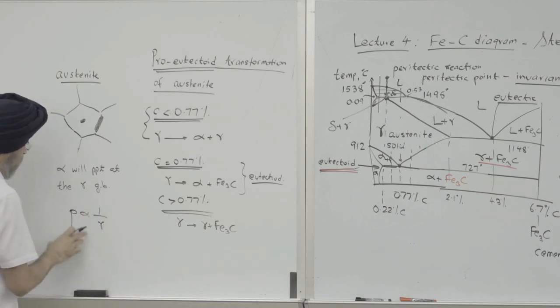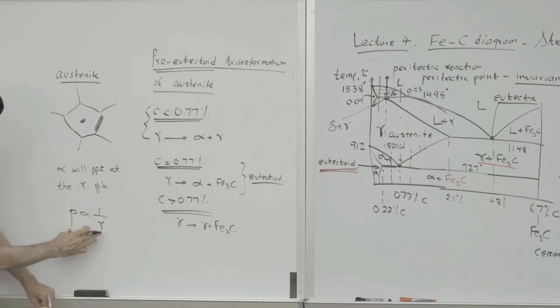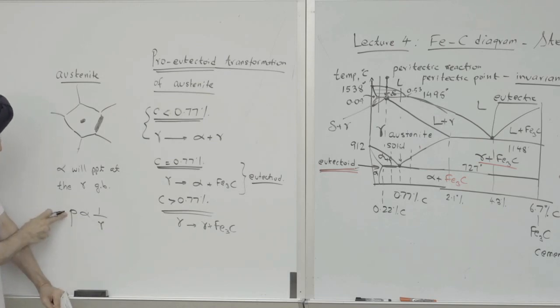So that's for gas bubble formation. The bubble has to be 0 to begin with, right? So the pressure to form the bubble is infinite. That's why bubbles do not form homogeneously within the liquid. They form on surfaces where it's more energetically favorable to form that bubble.